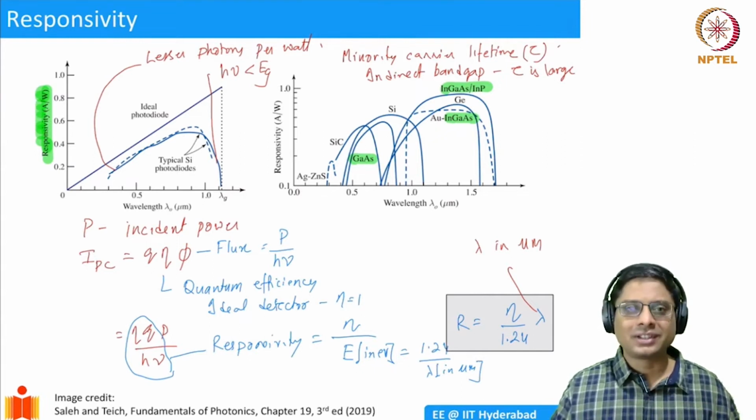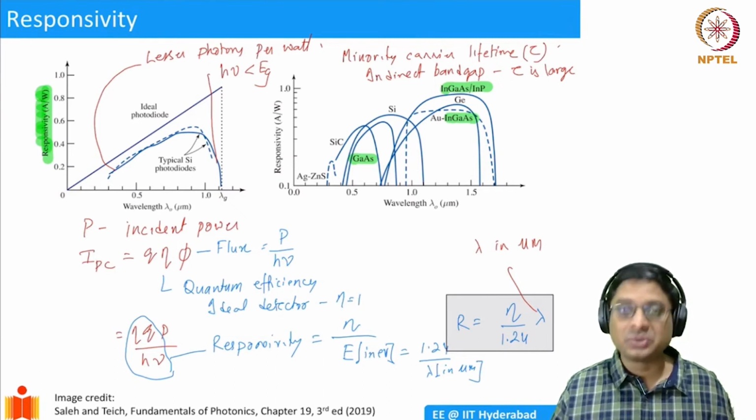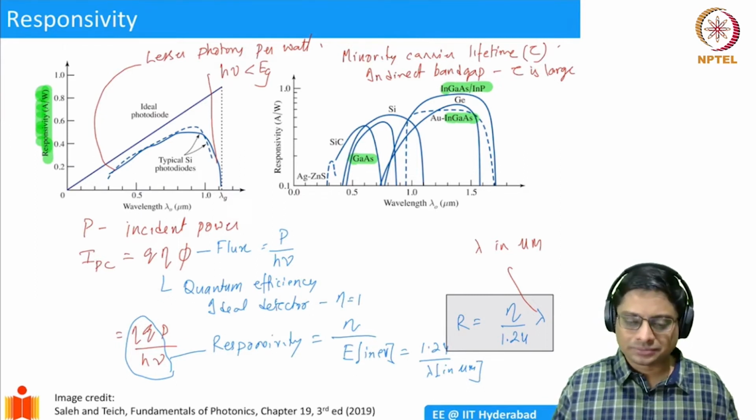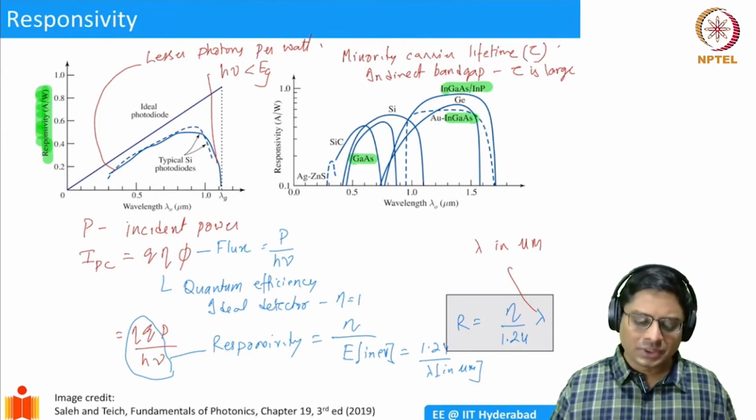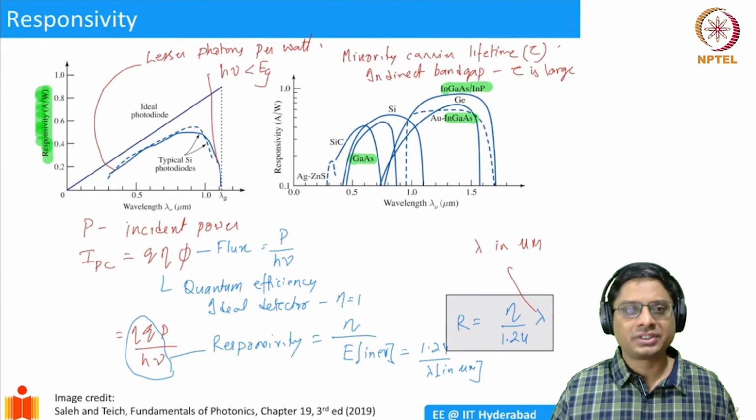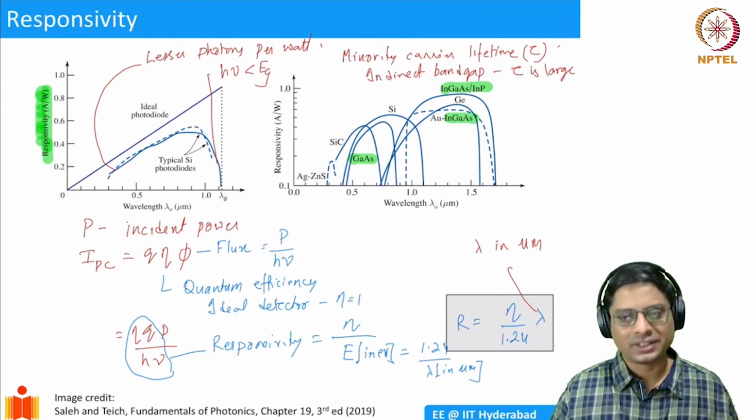Well, for the same reason, in silicon you can also collect these electron-hole pairs efficiently. That's why a silicon solar cell behaves reasonably well. If you build a gallium arsenide based solar cell, that's even better. Of course, we do that. It has much better efficiencies, but it's expensive. So silicon is cheap, so we try to use silicon solar cells. Similarly, you can make photodetectors out of silicon and germanium, and they still work.